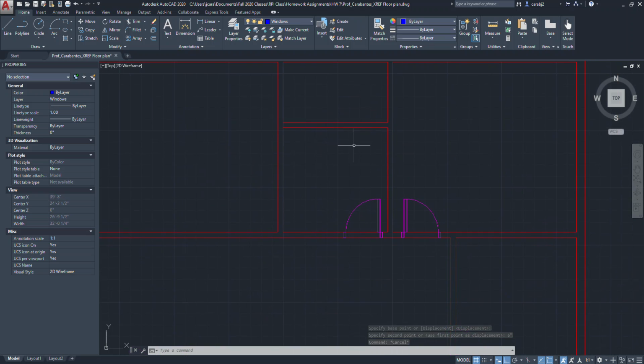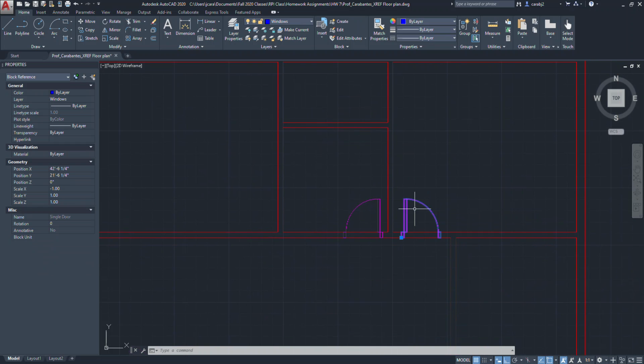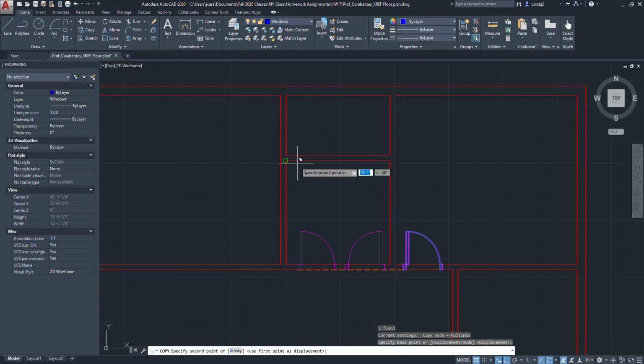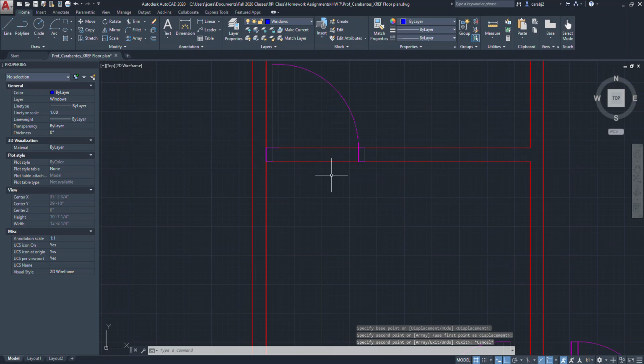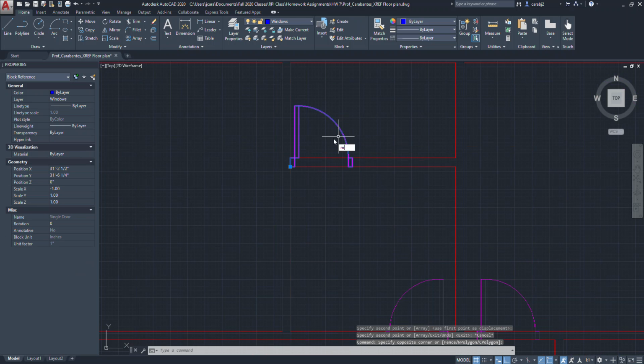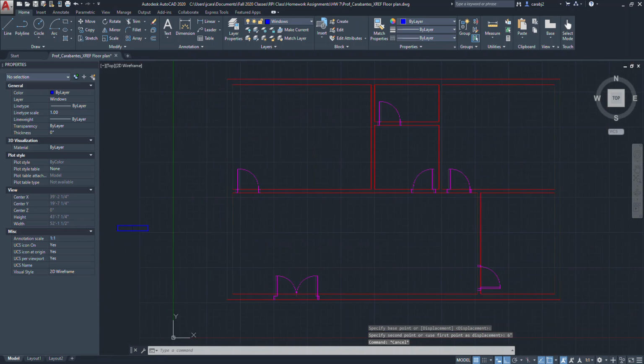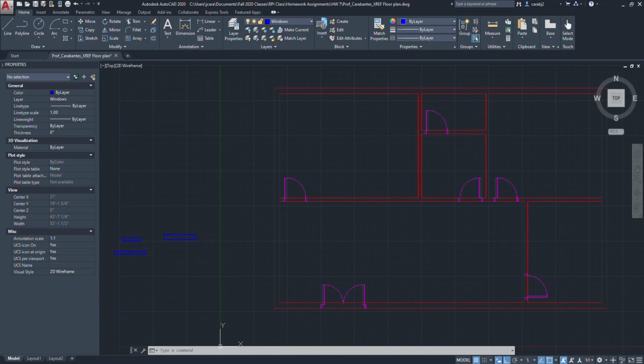So then what you can do is just add another door here. Let's just copy this one. Move it over 6 inches. And so now just make sure all your rooms have the doors. If you want them flipped the other way, you can make that as well. Just make sure that they are at least 6 inches off of the walls that you place them on.